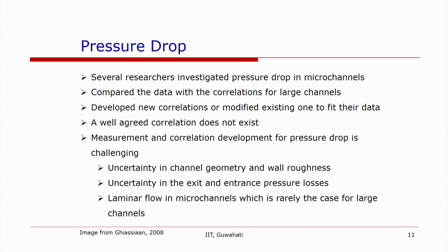So, we have looked at how the void fraction measurement in microchannels depends on a number of parameters, such as the homogeneous void fraction or homogeneous mass fraction, the density ratios, viscosity ratios, the ratio of the two velocities or the slip ratio, surface tension, and the channel diameter.